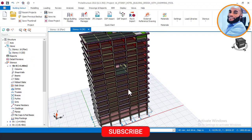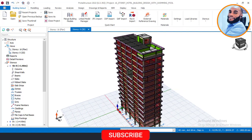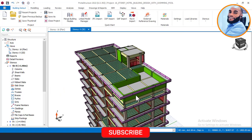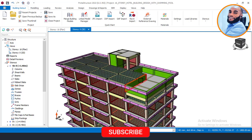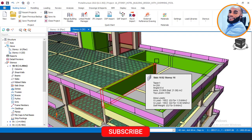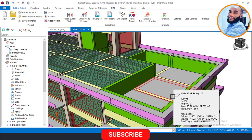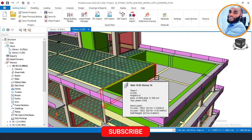So we have done many things about that, and then we modeled this pool at the top here. We modeled a swimming pool in part 11. So on this part 12, you have seen how we have just applied or defined the weight, like the effect of water on these walls. Okay, you can see that we have defined a water load of 13.63, which is the pool water load, on this wall, on this pool wall here.